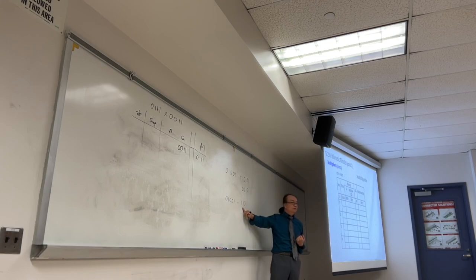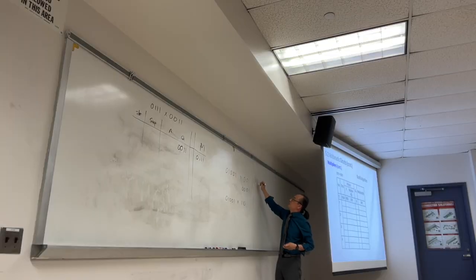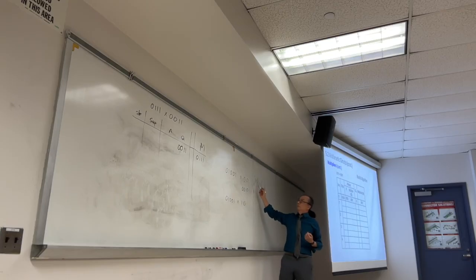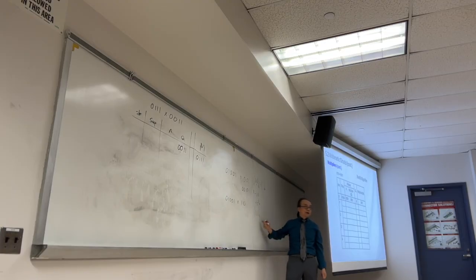Now we need to make this into 5 bits. So for example, let's have this as 2's complement. Find the equivalent decimal number. What is this? How do you know? I don't know. So we need to take the 2's complement. Reading from left to right, underline the last 1, put the negative, 0, 1, 0, which is negative 2 in decimal. Okay? Now, if we have 1, 1, 1, 0, let's find out. So the last 1 is this, negative, 0, 0, 1, 0.